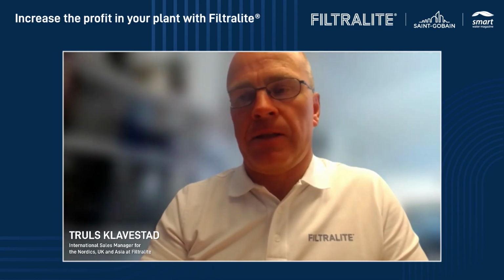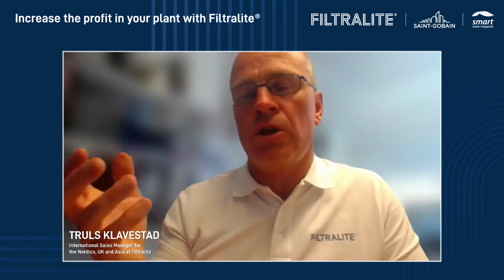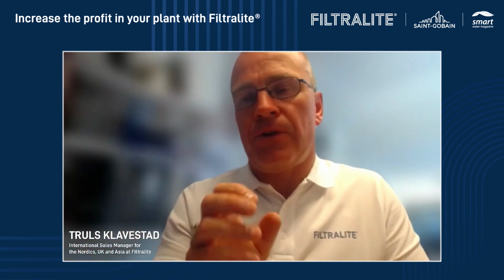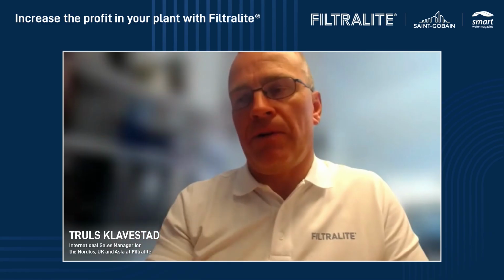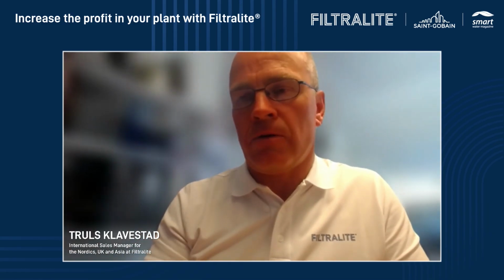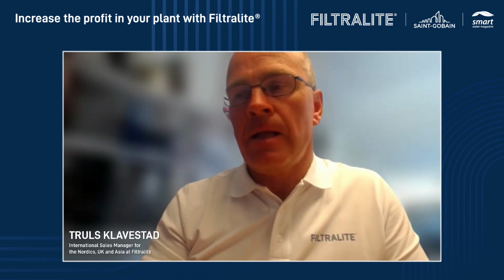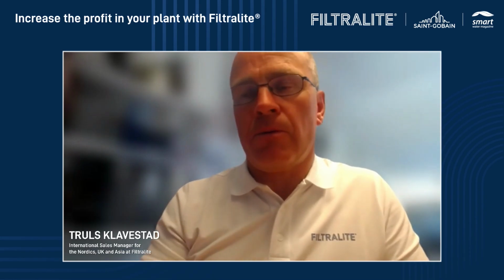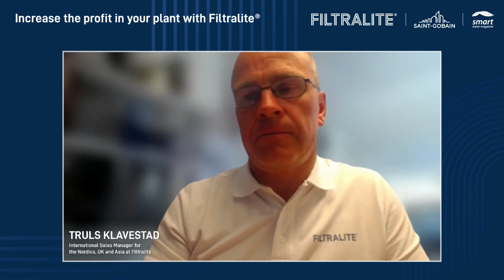in the filter. But if you have biological filtration, then we don't recommend that at all, because the oxidizer will penetrate into the pores, and it takes a long time before you have replaced all of it. So for all biological filtration, don't use any oxidizer that can penetrate into the pores of the material. But for sure, it doesn't matter what kind of chemicals you're using, they will never dissolve Filtralite.